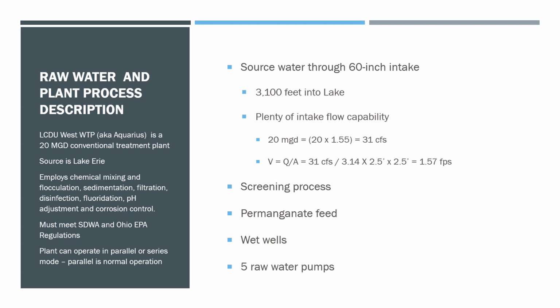As I mentioned before in other modules, engineers like to design water pipes to handle somewhere between 1 and 5 feet per second velocities. Anything lower than 1, you're going to have pre-sedimentation of organic material and some inorganic fines. Anything greater than 5 feet per second, you're going to have premature wear of the pipe.